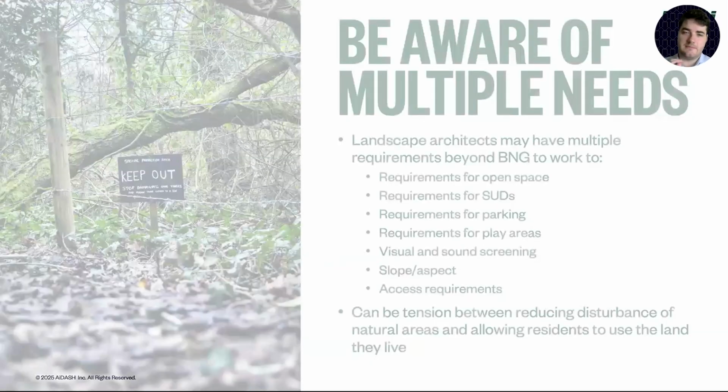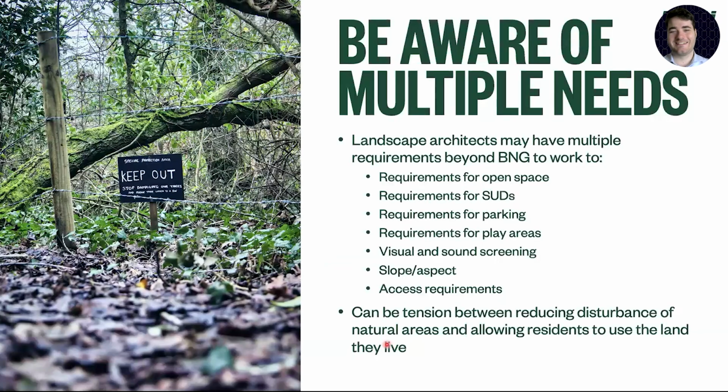Be aware that there are multiple needs with the landscape architect. They might be trying to create open space. They might need alternative space for people to use for, say, dog walking or whatever, which takes pressure off natural spaces. They might need to put SuDS in, parking, play areas, visual and sound screening in the form of woodland or lines of trees. Slope and aspect will all impact what the engineers can do, and obviously access.